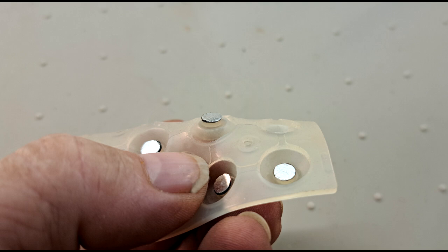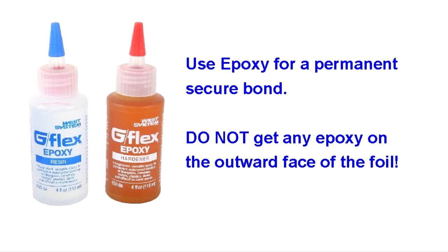The aluminum contacts will need to be securely attached and withstand the heat and cold of the elements, so you must use reliable glue. Quality epoxy will work well. Do not use ordinary white glue. It does not stick to non-porous surfaces reliably. Be sure there is no glue on the contact side of the foil.